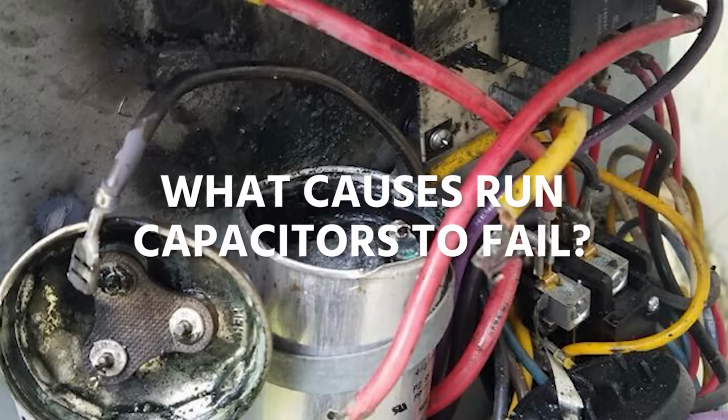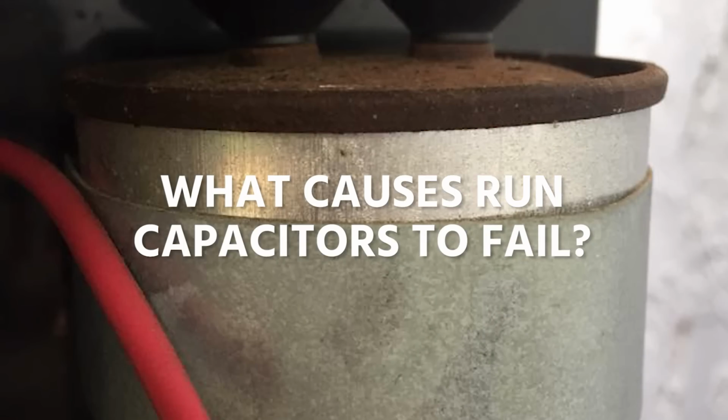So if your frequency stays the same, and your capacitor has a certain capacitance rating, then the amount of electrons that can go in and out of that capacitor just fluctuates based on the voltage. If you think of it like that pressure tank for the pump, it can receive electrons, it can store them, and then it can release them. That's essentially how it works. And as the phase changes, it's constantly storing and releasing 60 times per second. So we're going to explore some of these things and see if we can test and prove exactly how this works, and give you a better sense of what can actually cause a capacitor to fail.